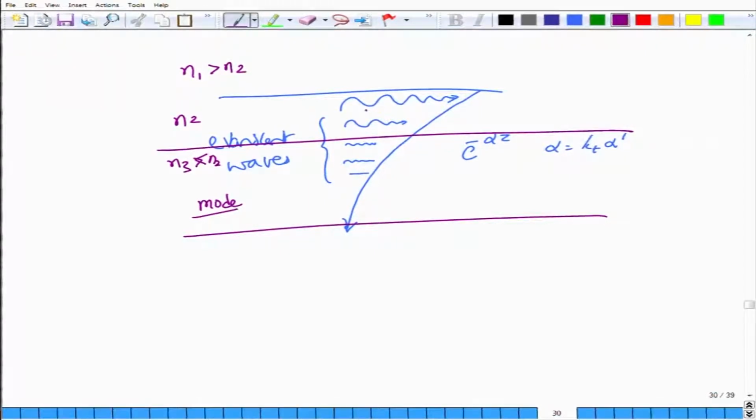So this is the way of what is called evanescent wave coupling into optical waveguides, which was very important in the 1970s and 80s when optical integrated circuits were first developed. Even today this is sometimes used. Instead of having any generic boundary, you actually put in a prism, such that you send light into the prism but you have the prism slightly above the optical film.